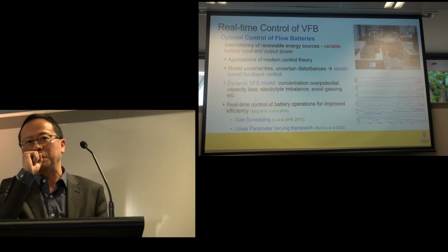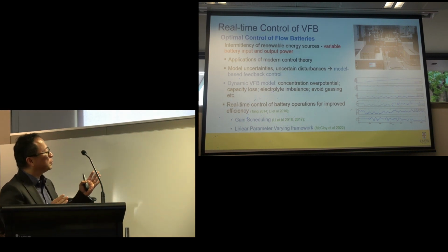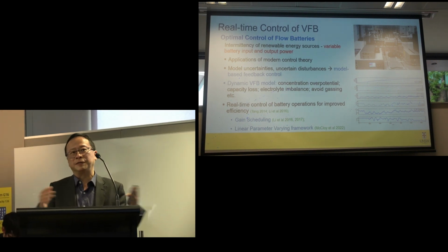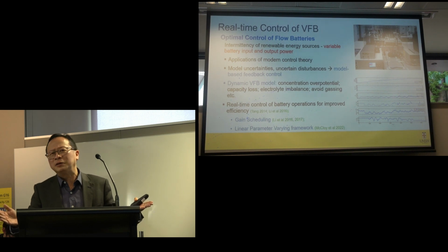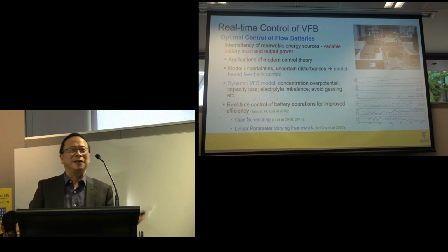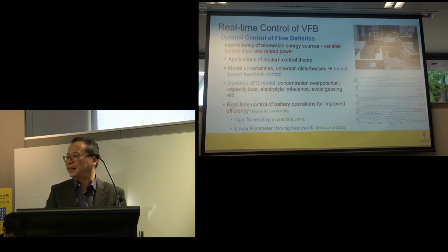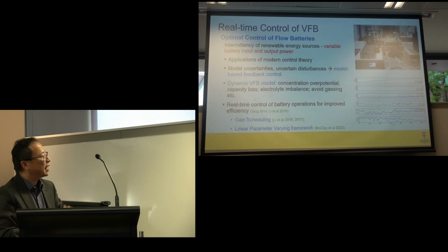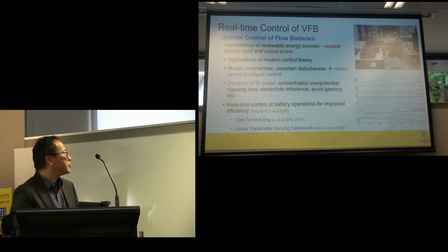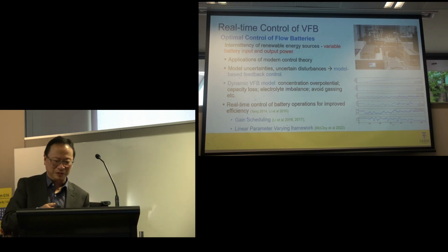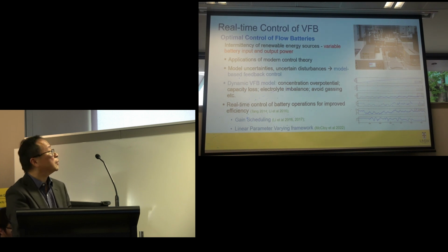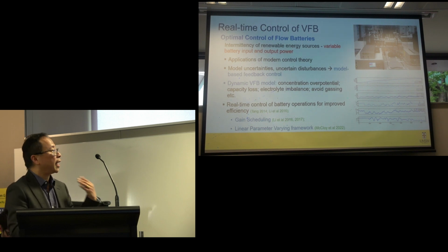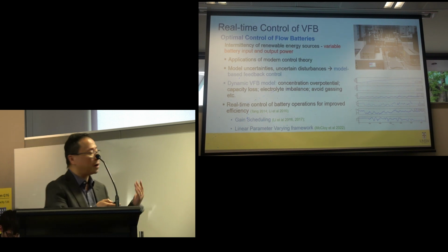I remember the day Stephen came to my office. He was looking at the optimal flow rate control for the vanadium flow batteries over a large range. He said, "Oh no, the PID control did not work." I said, "Fantastic, then we can try some nonlinear control strategies." So we worked on the gain scheduling control, and later on we worked on something called linear parameter varying theory for the control of the flow rate of the batteries when we have time-varying charging and discharging current, and dealing with the model uncertainties we have.